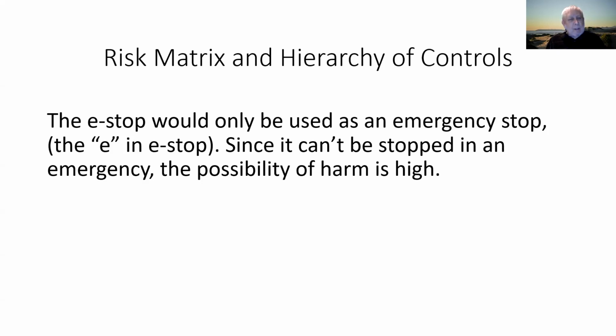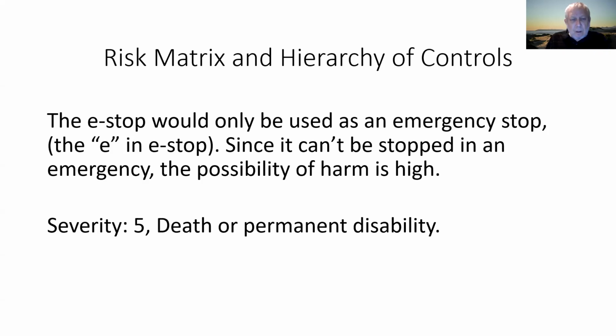Since it can't be stopped in an emergency, the possibility of harm is high in an emergency. If there's not an emergency, then it wouldn't even be used. But the severity is really high. Chances are, if an emergency happens where you need to stop that machine and you can't, it's probably going to do some pretty serious damage to somebody. So the severity is 5, death or permanent disability.